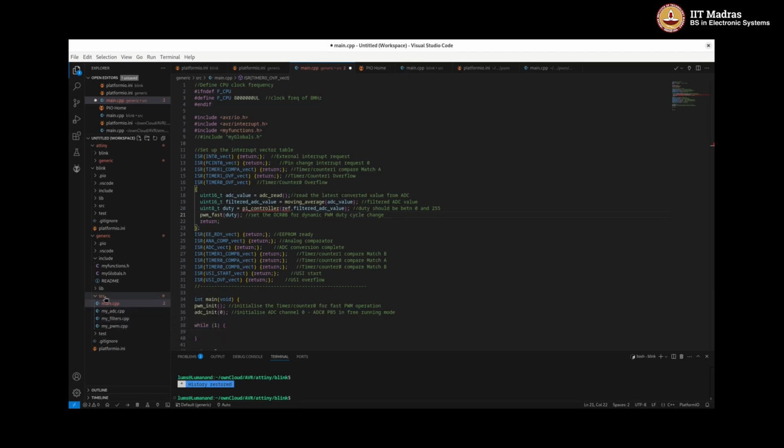And this function needs to be created. So go into the source folder, open mypicontroller.cpp, a new file, and within that type the function with the algorithm that we discussed for the discrete PI implementation. Then after that, go into the myfunctions.h and define the profile of the function that was created in the source folder.